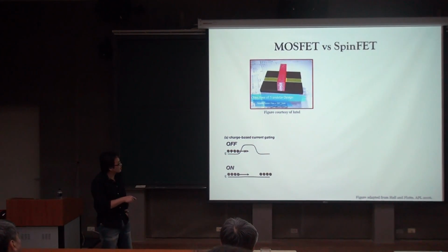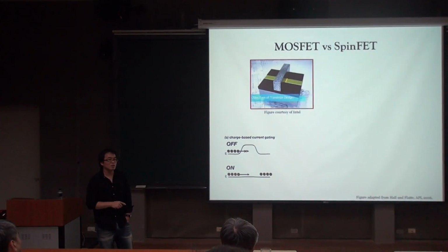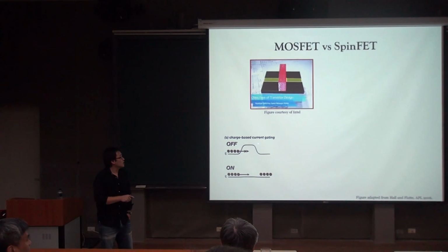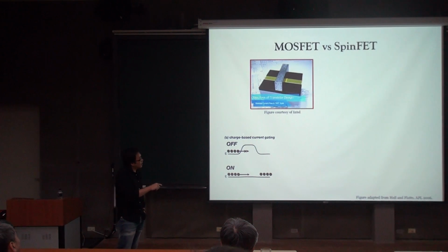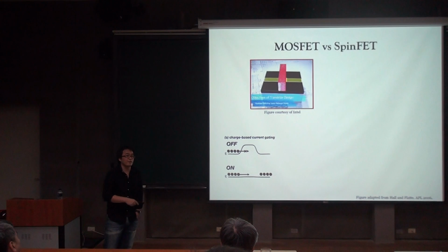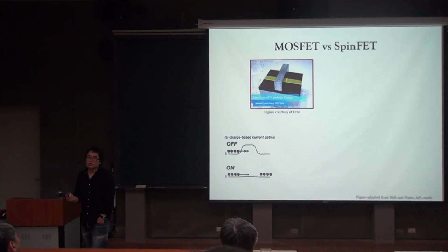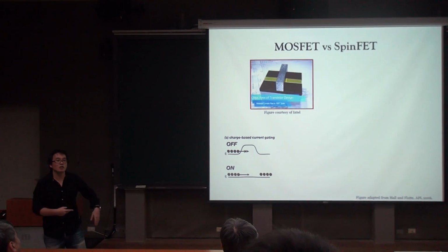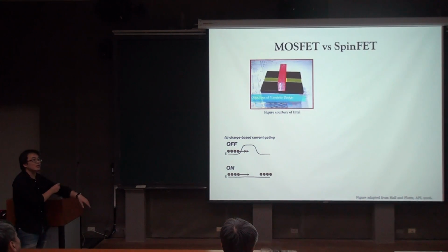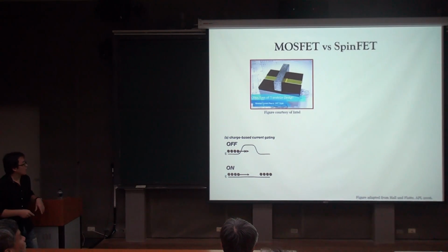Right now the operation frequency is about gigahertz. Another problem is that we try to reduce the length of the barrier. If it is 20 nanometers now and becomes 5 nanometers, from quantum physics you know there's always tunneling current. So even though you have the barrier, the current can still go from the left to the right, which gives you the on state. This is why there's no off state when you have a very thin gate.